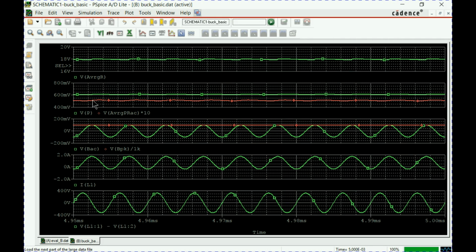And this is this component of the copper loss. This is the copper loss. Now, combining these two into the estimation of the hot spots, we get 18 degrees centigrade above ambient. Okay, so this is just the basic information that we are getting.